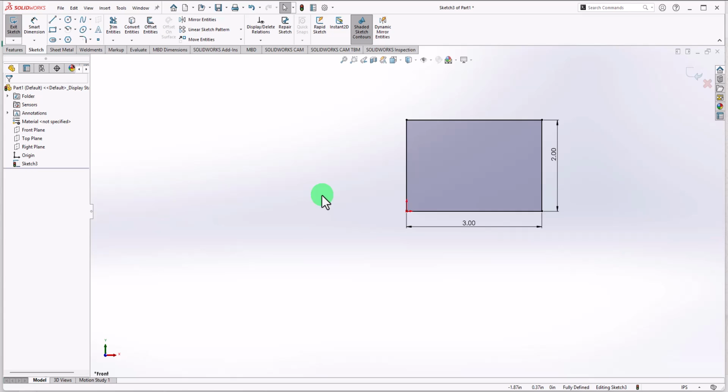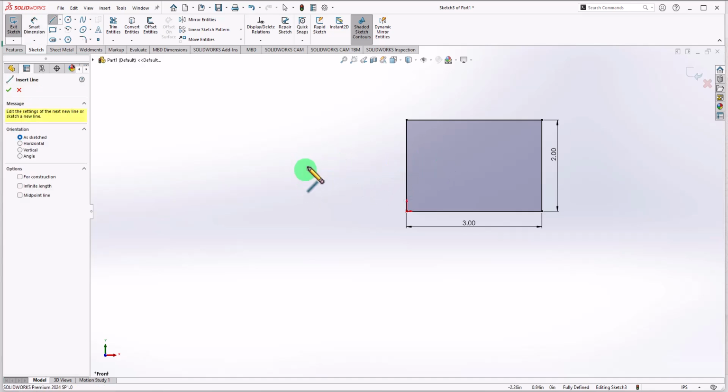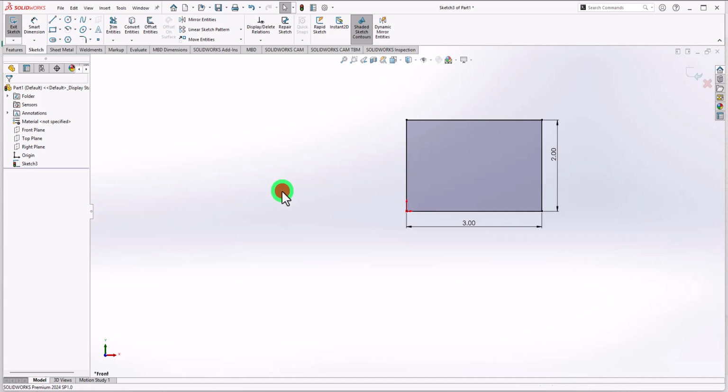Another quick way is to use a mouse gesture by simply right clicking, pressing and dragging the mouse in the left direction. There will be 4 mouse gestures presented here: the line command, the dimension command, the circle command and the rectangle. At the initial stage there are 4 gestures available. By simply highlighting a command, you can quickly activate the line command, the dimension command and other commands. At the first stage, the default value is set to only 4 commands.